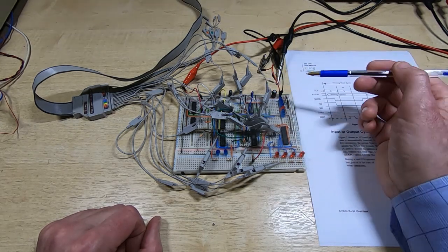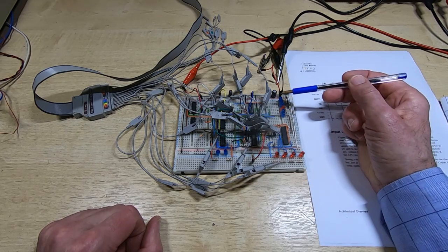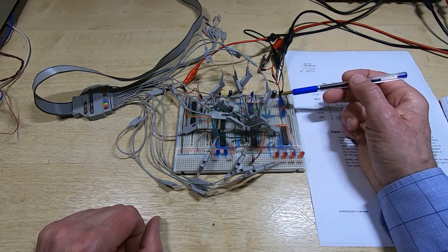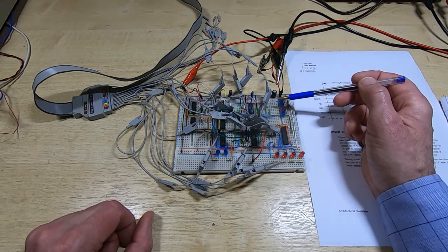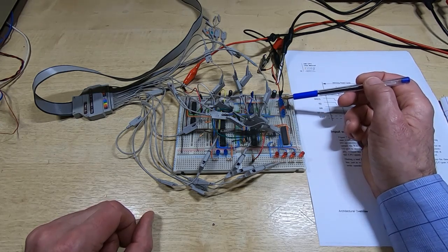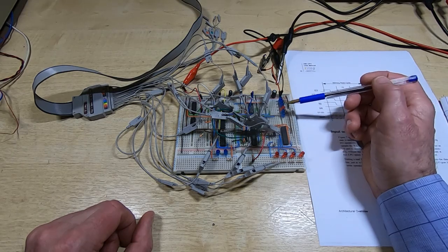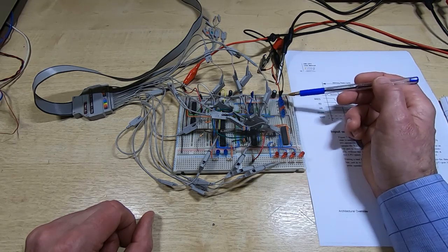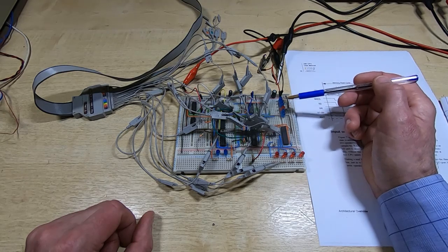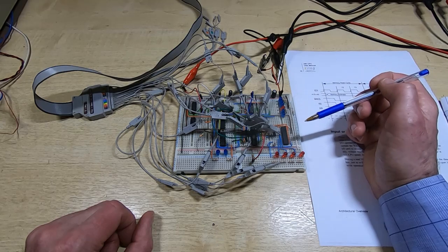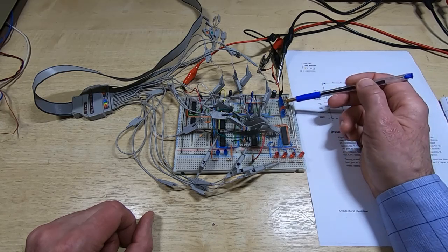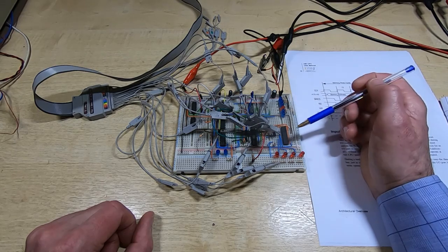So the way this works overall is the input that triggers it and starts it working is the DRQ line from the floppy drive interface device. That goes high whenever the device has a byte waiting to either be written into the floppy disk if it wants more data, or if it has a byte ready to be read from its internal data register and sent through to RAM.